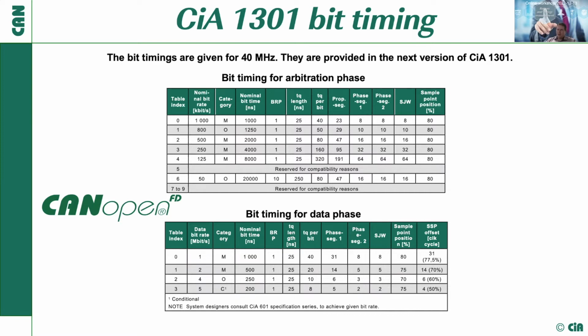Furthermore, we have now learned about the usage of the CAN FD SIC transceiver. The CAN FD SIC transceiver has the capability to calm down ringing. So if you have a very disturbed network, the SIC transceiver can calm down the ringing, and therefore you can run CAN FD also in networks deviating from the line topology. That's the good news. But the problem is that, for this calming down of the ringing, they take a bit from the propagation segment, and therefore the overall length is a bit limited, or respectively the communication speed that can be achieved during the nominal phase is limited.